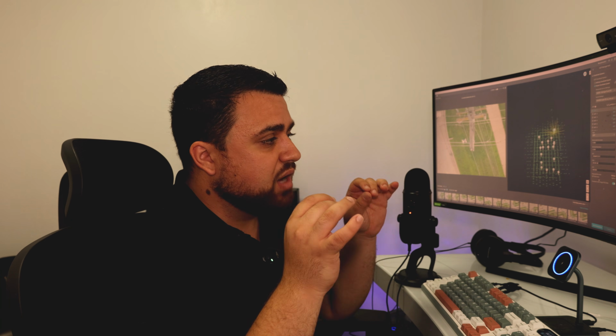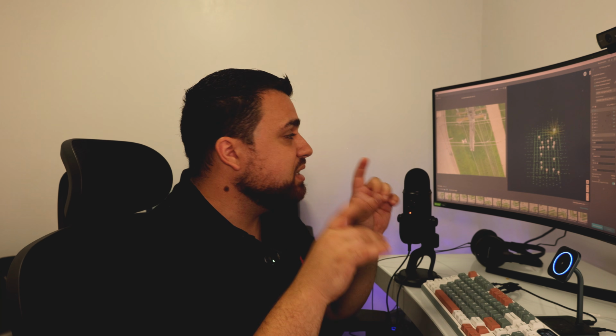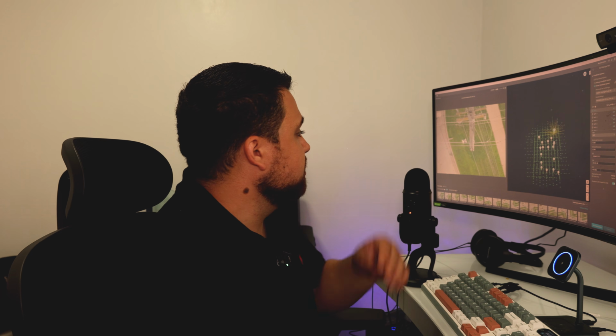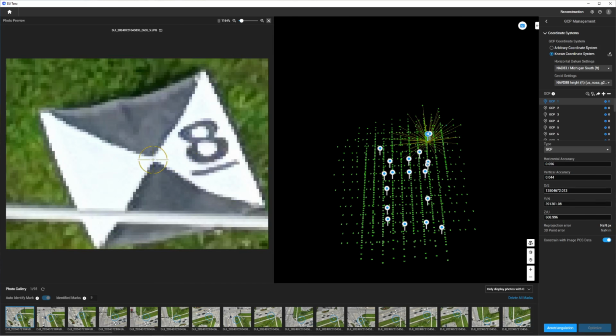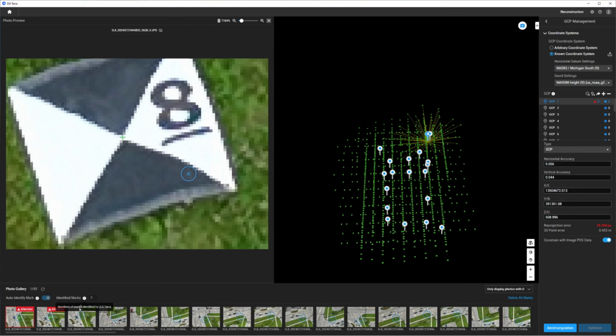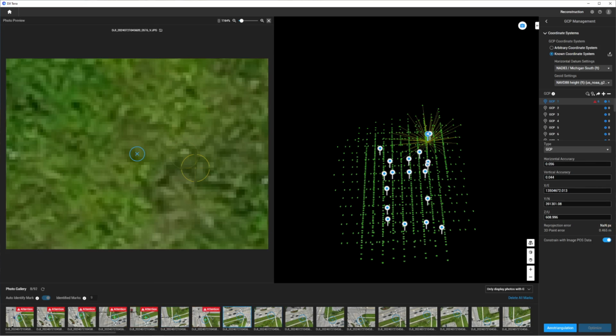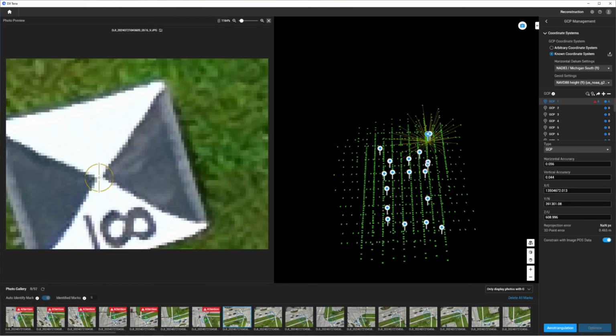And now we're just simply going to georeference the position of each of these points in the imagery that we collected. The first one is a ground control point, so all I'm going to do is see where it appears in each image. So there it is in this image, here it is in this image, and I will now select the position for some of the images. It doesn't have to be all of them. Now we've identified all of the ground control points.